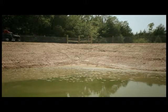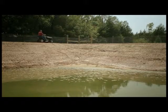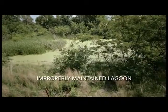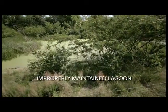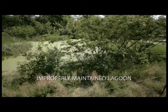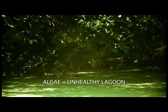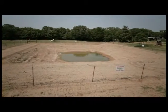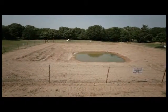Keep the grass mowed inside and outside the fence surrounding the lagoon. Cut down any trees and shrubs that start to grow around the lagoon, both inside and outside the fence line. Do not dump trash or other debris in or near the lagoon. A healthy lagoon should not be overgrown with algae, and it should not have an offensive smell. Proper lagoon operation and maintenance is necessary to prevent mosquito problems.